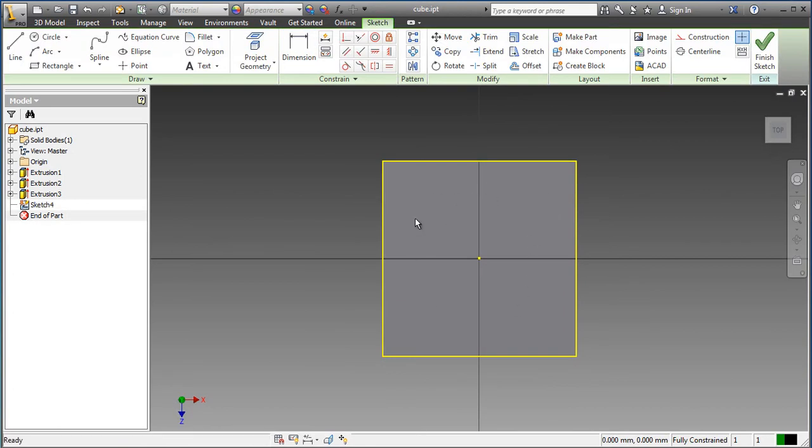Now on here we're going to have to draw 5 dots, and this time because it's a bit more complicated drawing 5 dots, if we've got a complicated drawing and we're doing it on paper, we use construction lines, and that's exactly what we're going to do here. We're going to add some construction lines to this surface so that we can position our circles very accurately. Now the great thing about construction lines is that when you draw them you can see them, but when you print out or when you finish the drawing they remain invisible. So you select the line tool and then you go over here and you click on construction to make sure the lines are construction lines.